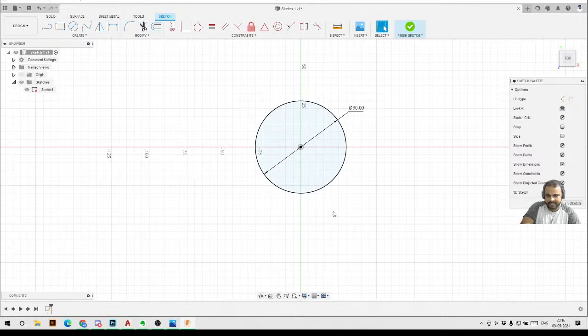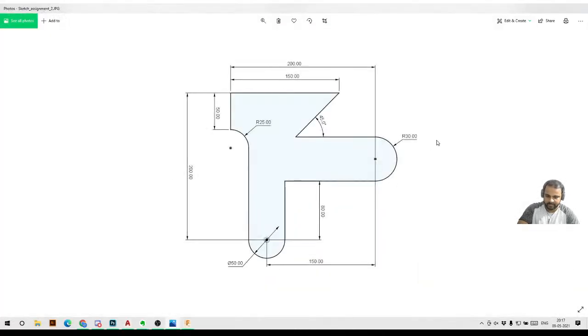I know, let's say if you want to present a radius in our technical drawing, then how can we change that? That we can do in the technical drawing, when we start creating the drawing portions. I already told you here inside this drawing. Those things we'll do later, but these sketches are only a reference. We can put the dimensions anywhere, like this, like this, like this. It's up to us. The best practice is to always keep dimensions outside your object, so things will be more visible to us, and even if we come back after 2 or 3 days, we will be able to read our sketches. That's why it's always good practice to keep things outside and organized, not overlapping with each other. Okay, so we'll move forward.